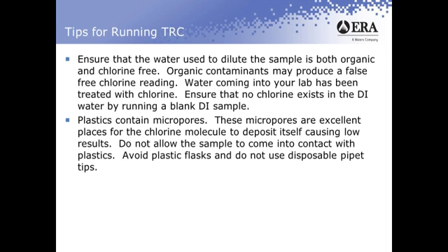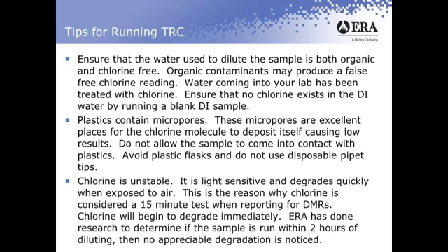And I would highly recommend not using disposable pipette tips, such as the ones that come with Eppendorf pipettes. I would highly recommend that you use Class A glass pipettes for your dilution, or what also works really well are gas-tight syringes. Again, we want to remember that chlorine is very unstable. It is light sensitive, and it degrades quickly when exposed to air. This is the reason why, when you're doing your DMRs, chlorine is considered a 15-minute test. That's why you have to run it quickly. Chlorine will begin to degrade almost immediately when exposed to air and light.